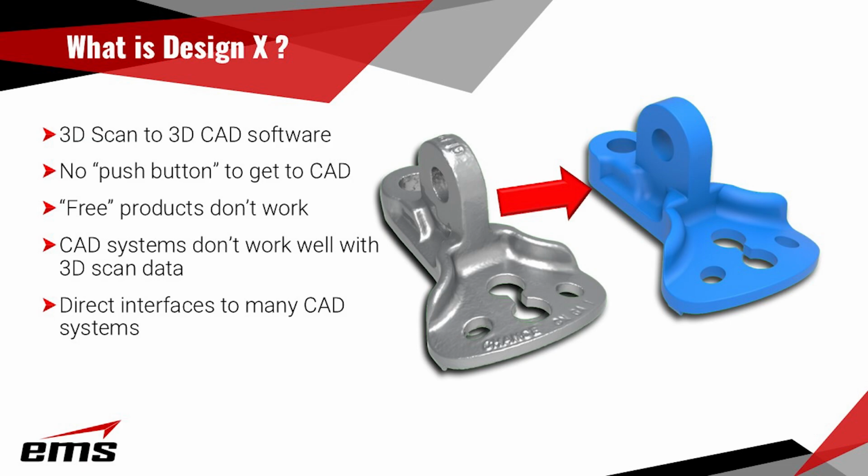Now, there are many free products out on the market that do mesh cleanup and do some basic stuff, but to go to a CAD model, especially a more complicated CAD model, they just don't work very well. Okay, and the other thing with Design X is you can output neutral CAD files like STEP, Parasolid, IGES, but then it also has a direct interface to many CAD systems, and we're going to demonstrate that later and show you the value of that.